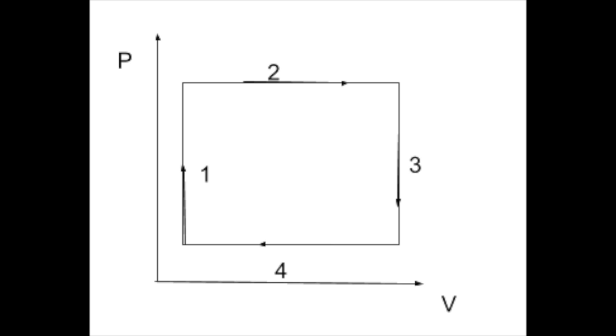Since the expansion and compression of the piston is a cyclic process, the PV diagram should indicate the cycle by starting and ending in the same state. The first process would be isochoric expansion, since the volume is held constant. The metal cylinder, which starts in the cold bath, therefore a cold temperature, is moved into the hot bath. As the temperature of the metal cylinder increases, the pressure inside the cylinder increases as well. When this pressure is able to lift up the piston, and the pressure is able to counteract the weight of the piston and the surrounding atmosphere, this is where the process stops.